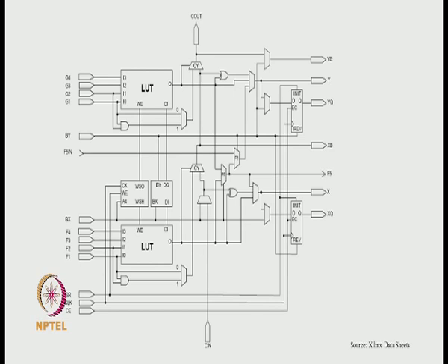You don't synchronize the reads. You could synchronize the read using the flip flop. If you don't, then you will see the variable latency, and if you use it for some precision, say you are trying to generate a waveform using a DAC, then you will find a jitter. So you should keep that in mind. That may not happen with the block RAM, where many times the output can be synchronized. But if you use a distributed RAM as a huge memory which is spread across and the read is not synchronized, then you might get variable read latencies, and in some cases it can affect your implementation. You keep that in mind.